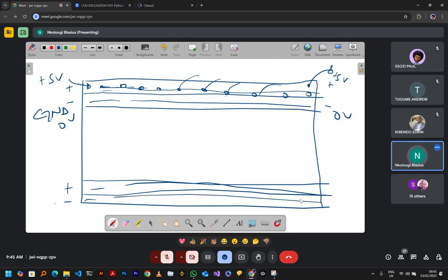So you can create your rail. Like I said, you have a power supply somewhere. You have a positive terminal and a negative terminal. So you connect from the power supply, you supply on this rail, and the negative, again, you supply on this rail. So that next time when you want to tap anything like 5V, you tap anywhere you want there.